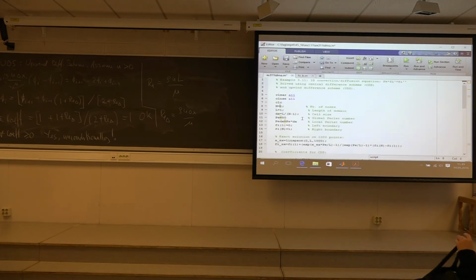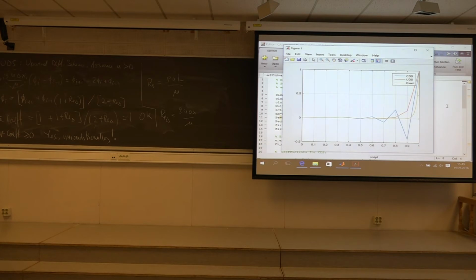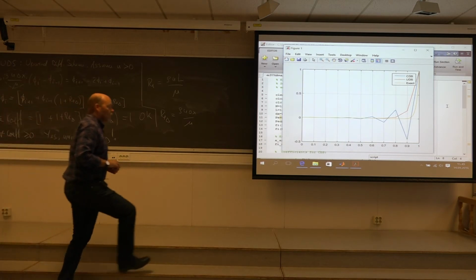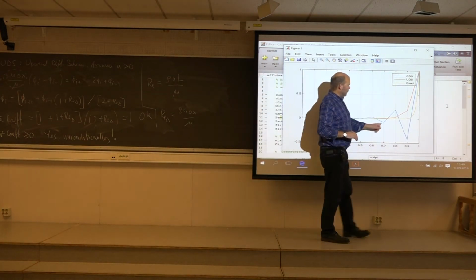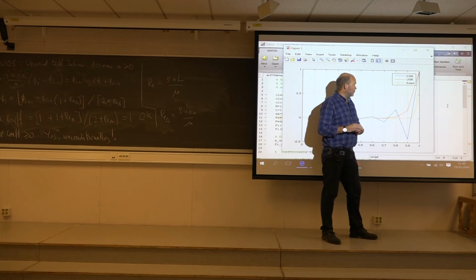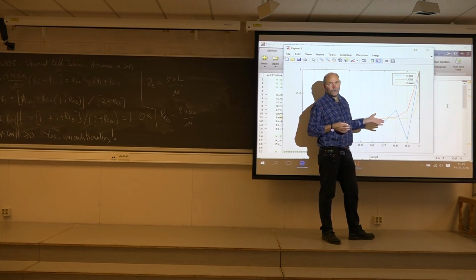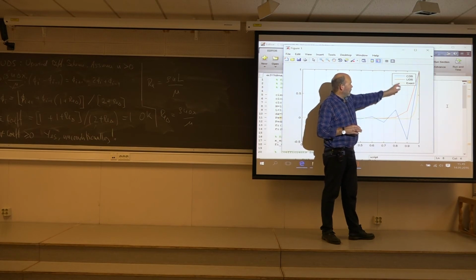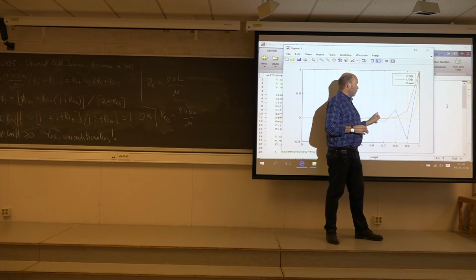And if we even reduce the number of cells further, you will see, oh yes, this is going really bad with the central scheme. You will start getting oscillatory results, and of course in a real problem it will blow up in your face quite rapidly. The Upwind scheme will be stable no matter what.